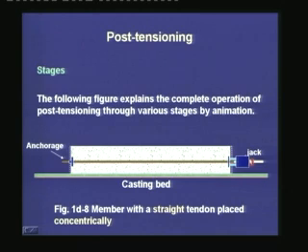When the jack applies tension to the tendon, the concrete member undergoes elastic shortening, and the tendon is subjected to the desired amount of tension. Then the jack helps the wedges to sit against the concrete member, and the extra amount of the tendons is cut off from the two ends.